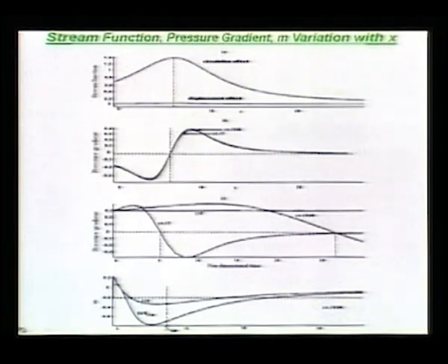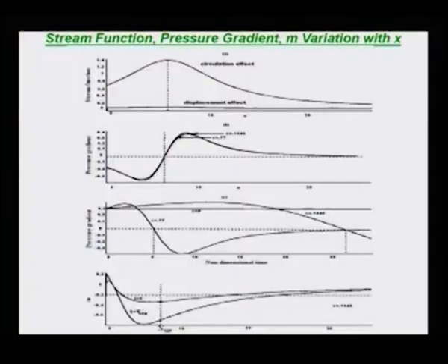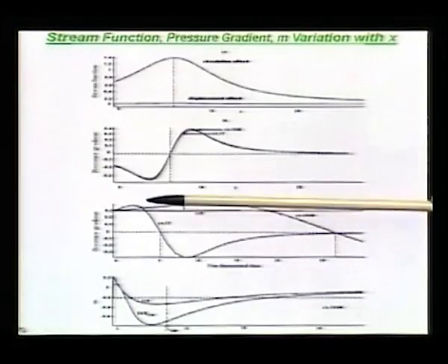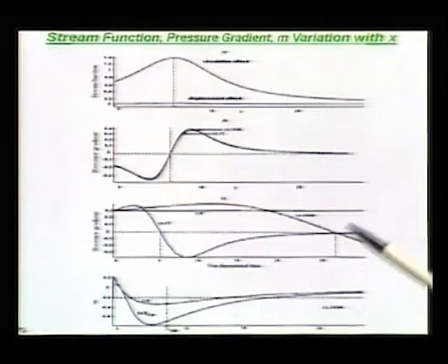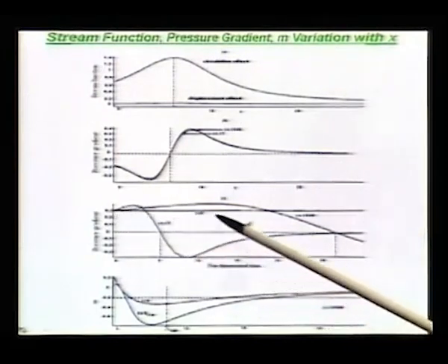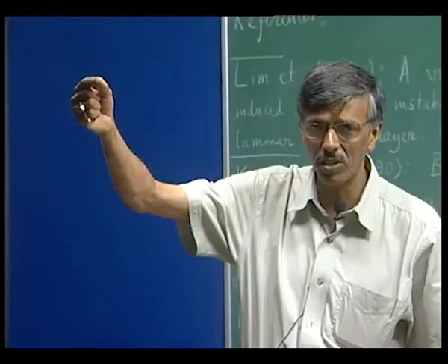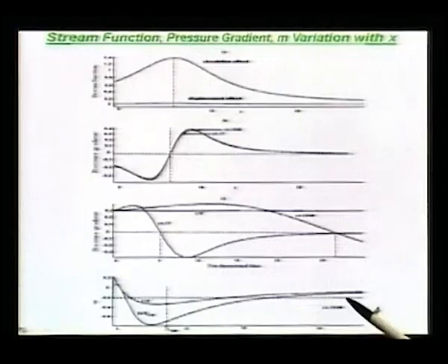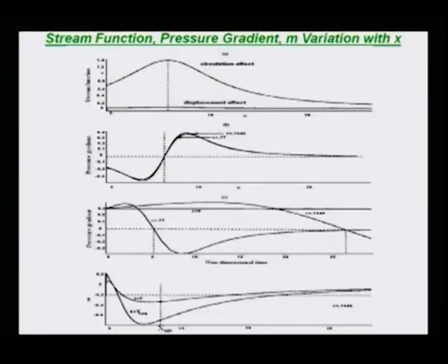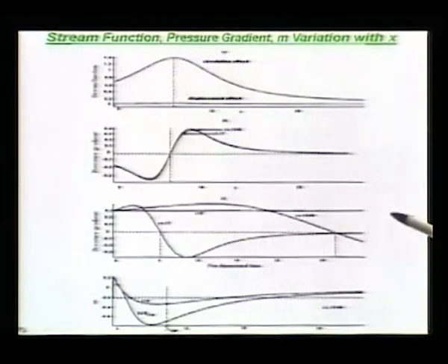What you notice is the following: if your vortex is not moving, then you get the case of C equal to 0, and in that case, at that fixed location the pressure gradient remains the same. And what happens is that it is an adverse position. So, you have put in the vortex at x naught equal to 1, and at x equal to 5 you are looking at it. So, what does it do? It basically creates an adverse pressure gradient ahead of it, and that remains invariant with time.